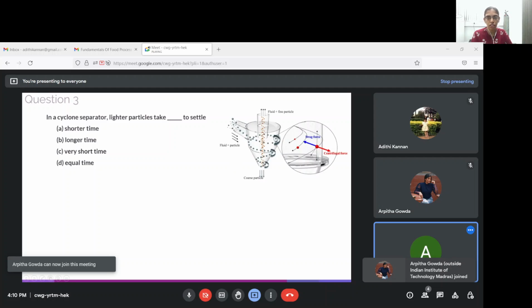As we discussed in the first slide, in a cyclone separator, you will pass in air with a lot of particles in it, and you need to separate these particles from the air to get cleaner air. When it enters the cyclone separator, it forms a kind of rotatory motion, thus experiencing centrifugal force. Because of this rotatory motion, it will often hit the walls of the cyclone separator, and once the particle hits the walls, it falls down due to gravity, and whatever remaining air is there will rise up in the cyclone separator again in the form of a vortex. Here you will get your fine clean air with only fine particles, and here you will get your coarse particles that fall due to gravity.